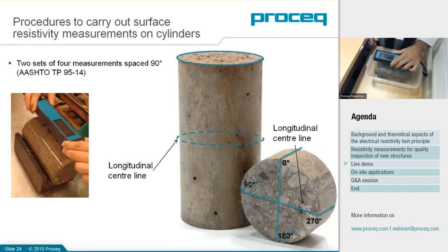As some question would involve what were the electrical parameters. This indicator tells us whether a 200 microampere or 50 microampere are driven through the outer probes, and the corresponding voltage is read in the inside probe. Okay, measurement stable. I will store it, and so on for all the required measurements.